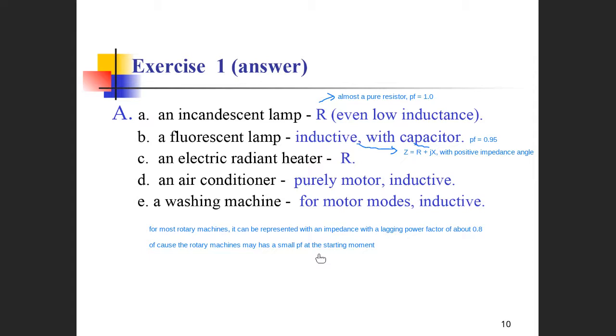Okay, so this is telling you how to represent given machines or given users in a single phase AC circuit. Now before we talk about tutorial examples 1 and 2, let's look at the data tables to try to understand, in the AC circuit, what it means by the right current carrying capacity, what it means by the cable size, and what it means by the voltage drops across the impedance in the single phase AC circuit.